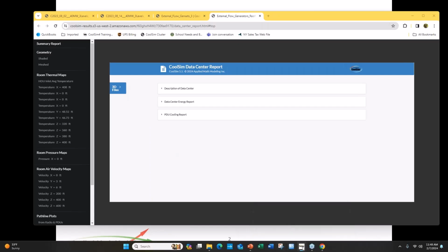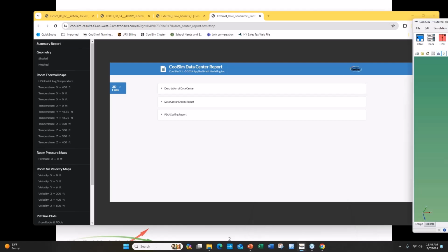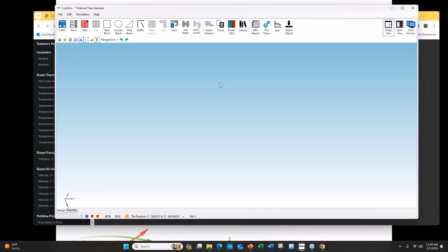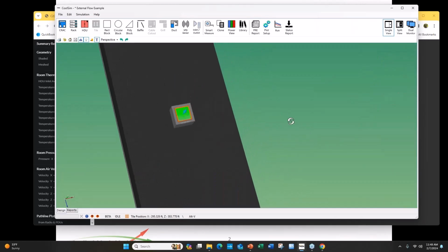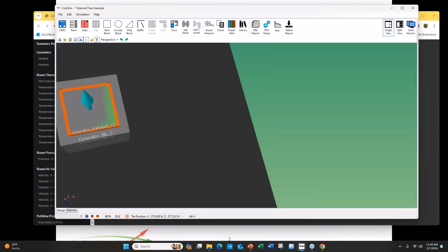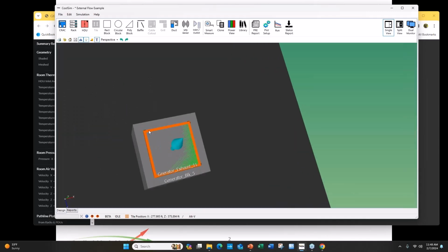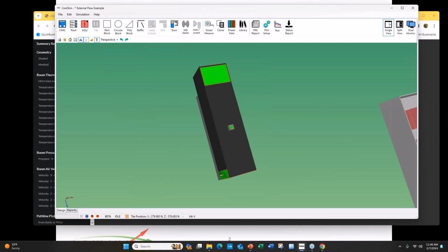So in making your inlets and outlets, and I'll use this image again, try to make the outlet as close to the size of the block as you can. You see it wasn't done right there. Here you see how the inlet, in this case outlet, is not quite the size of the block. You should make it the same size as the block so the mesh doesn't have to do a double mesh here. You're already meshing this surface, but you'd also need to mesh this surface independently, and that's a very small geometry for a room of this size.